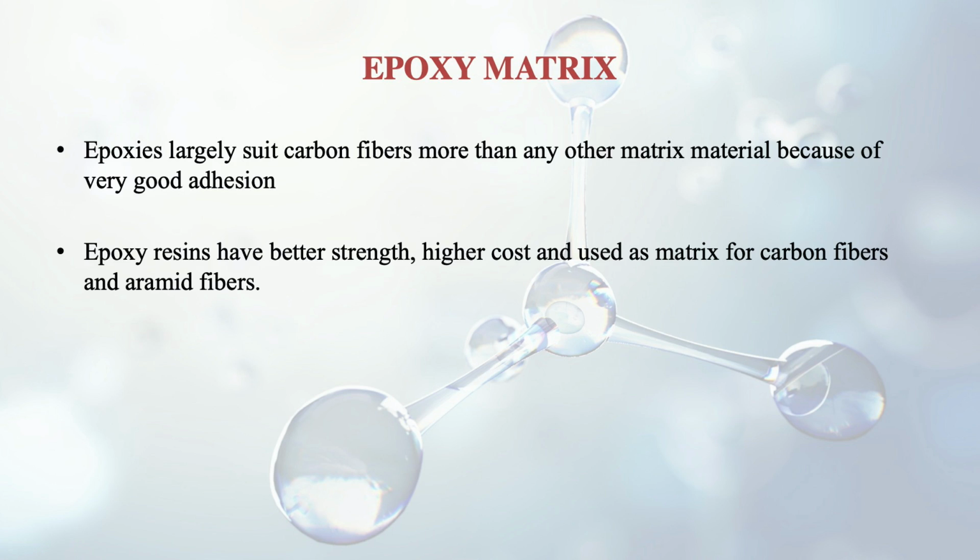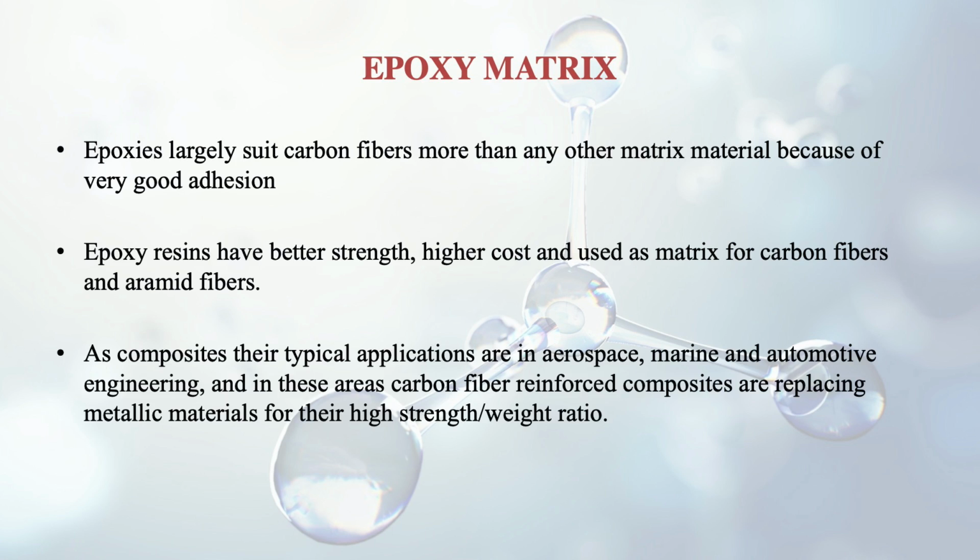So epoxy is a very good matrix material for carbon fiber. These epoxy resins have better strength and higher cost, and are used as a matrix not only for carbon but also for aramid fibers. As composites, their typical applications are in aerospace, marine and automotive engineering, and in these areas carbon fiber reinforced composites are replacing metallic materials for their high strength to weight ratio.